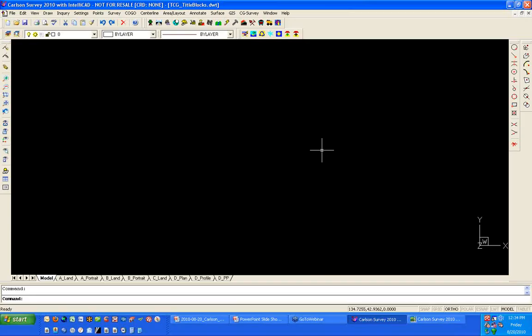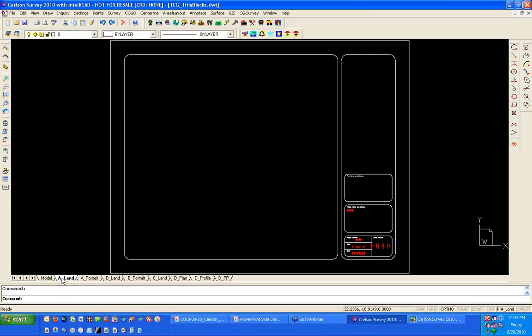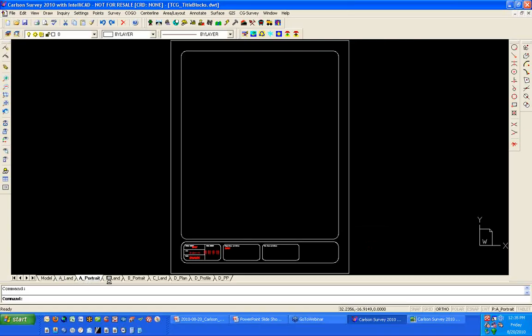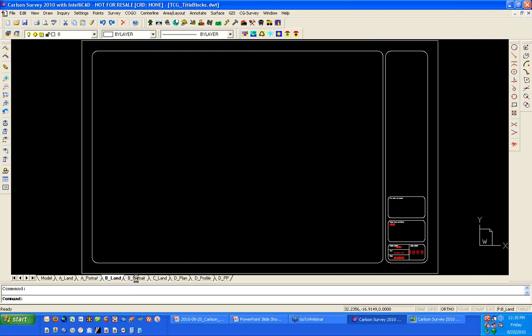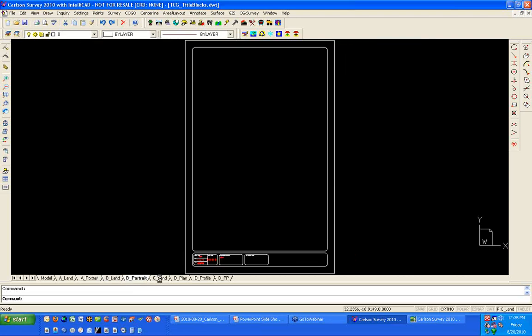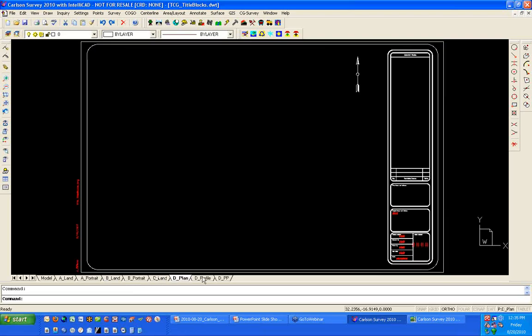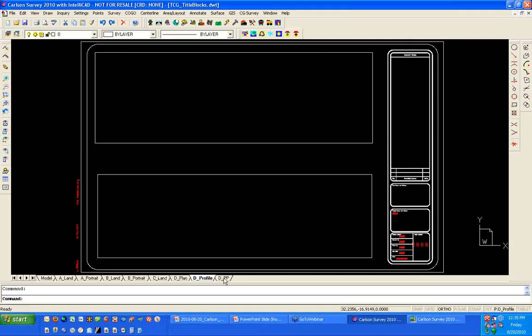And the first thing you notice is absolutely nothing. So in model space, in my container drawing, I have absolutely nothing. You can see I only actually have 2 layers in this drawing, even though it's a template. And if I go over and click on one of the tabs, you can see that the only thing I have in this drawing are layout tabs with my different sizes and orientations of title blocks.